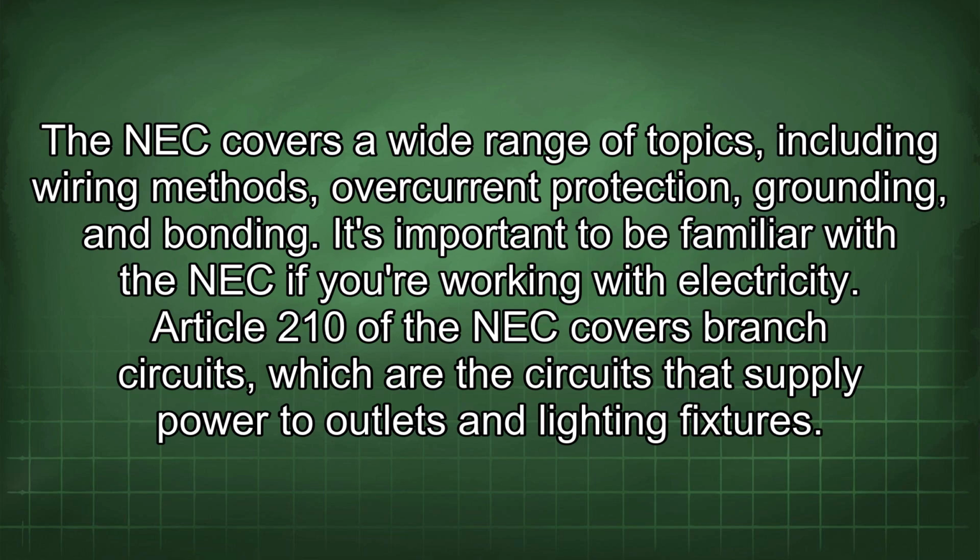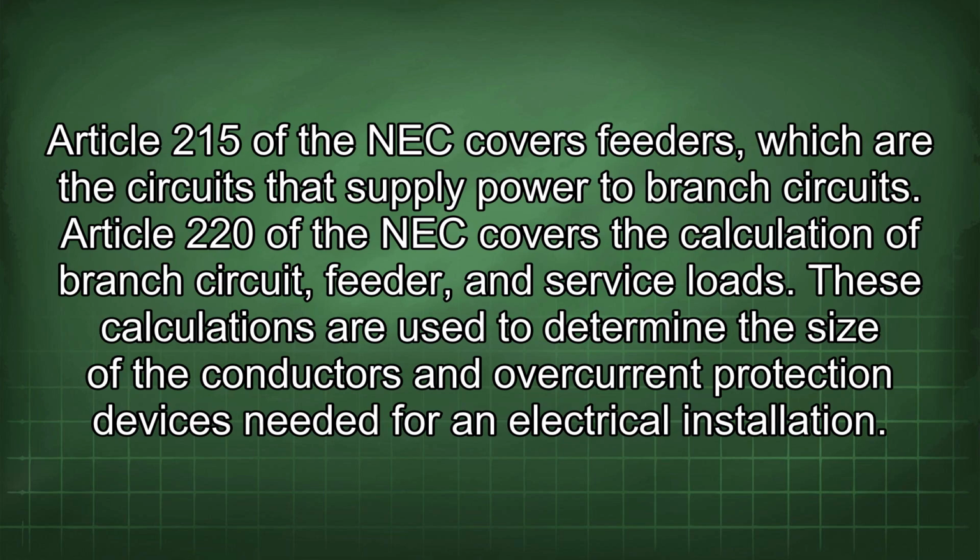Article 210 of the NEC covers branch circuits, which are the circuits that supply power to outlets and lighting fixtures. Article 215 of the NEC covers feeders, which are the circuits that supply power to branch circuits. Article 220 of the NEC covers the calculation of branch circuit, feeder, and service loads. These calculations are used to determine the size of the conductors and overcurrent protection devices needed for an electrical installation.